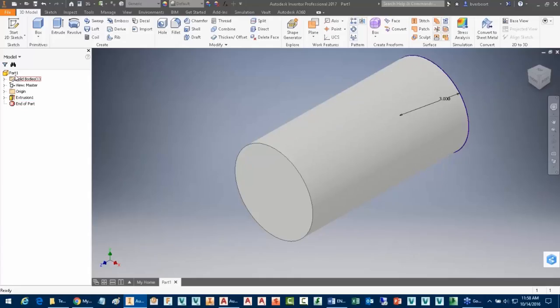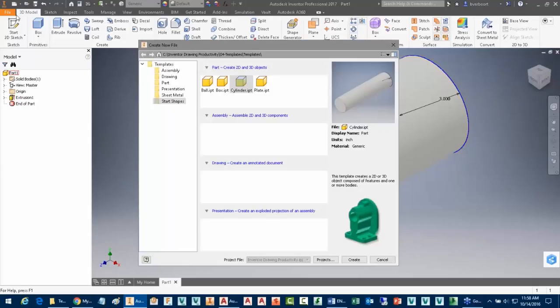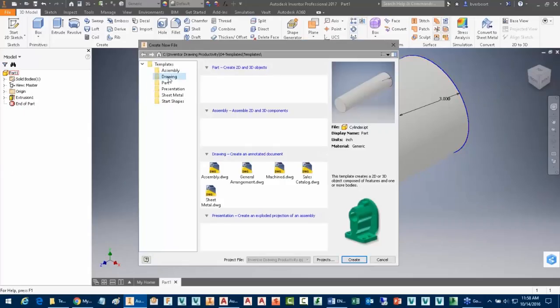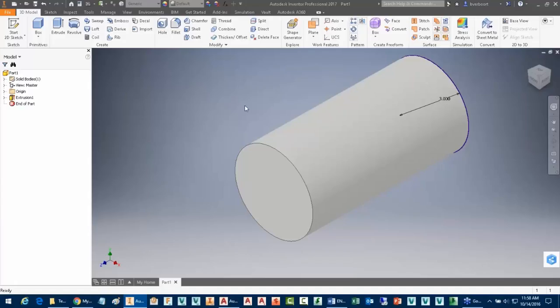So now when I create a new drawing for this, which gives me the ability here to create a new drawing as well, or New here, I could select the appropriate drawing template for a machined part, and it could even be for a shaft. Again, notes with runout and those types of things can be included automatically for those document types. Just try to remove some of that tedious effort from yourself and the users you might be trying to support.